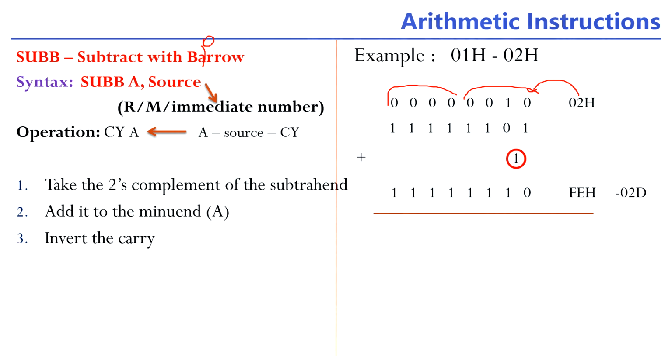This is the 2's complement, basically, you see here, right? These numbers, 1 and 0, this is the first complement, right? This one is the first complement of this, right? 11111101. We converted 0 to 1 and 1 to 0.